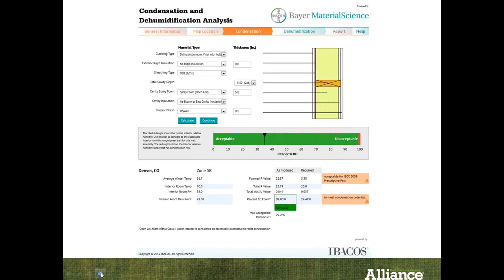Marty, there was a quick question here that says, but filling a 2x6 wall cavity with open cell foam in Minnesota does present condensation risk. Oh, I'm sorry, this is a comment. Because of the, it says OCSPF. Am I reading that? Open cell spray polyurethane foam. Thank you. It is not vapor impermeable.